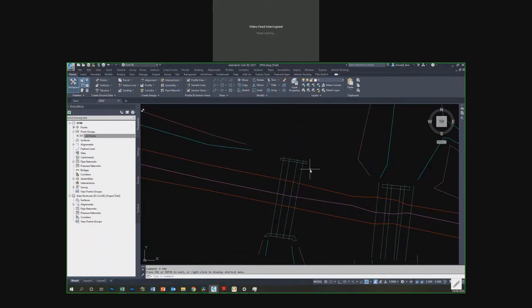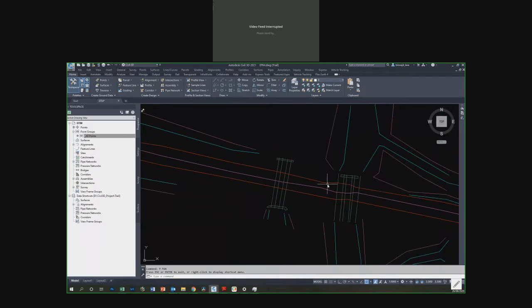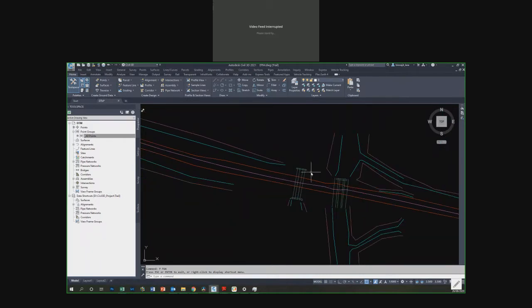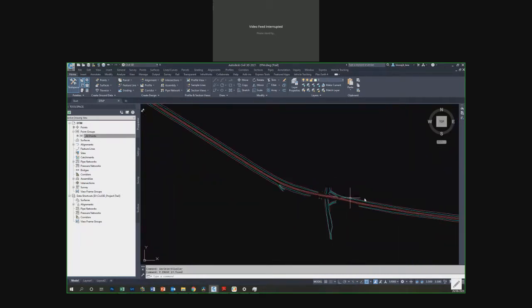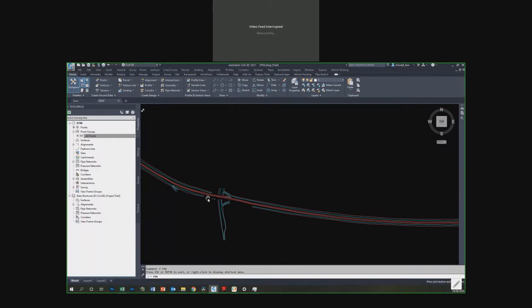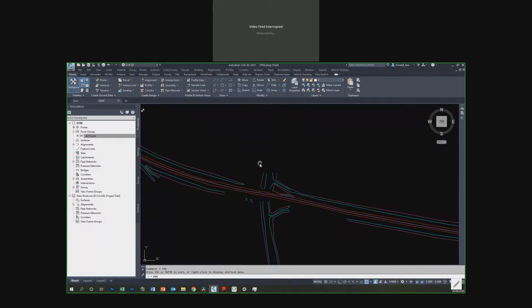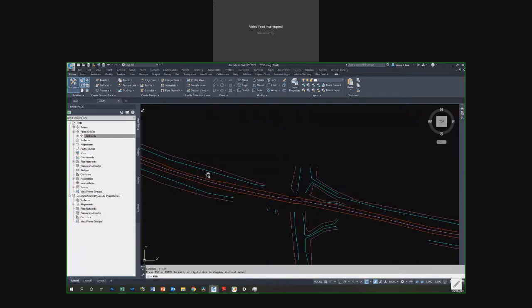The thing you should remember before preparing the DTM is that anything which is crisscrossing like this one, this is a marking of the culvert. You need the marking of the culvert, but not in DTM drawings. So just remove them. Anything which is crisscrossing, you need to remove. The reason is that whenever you are creating a DTM, these lines will be assigned as something called a break line.